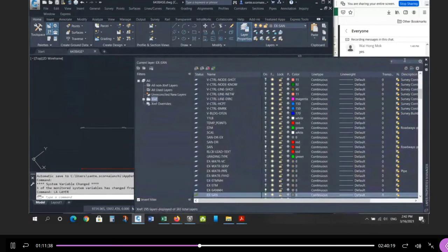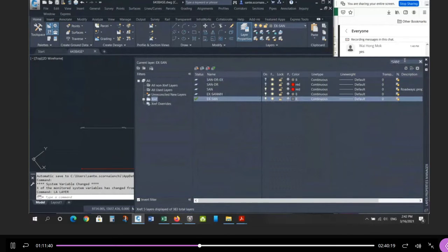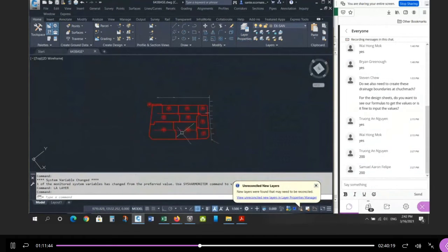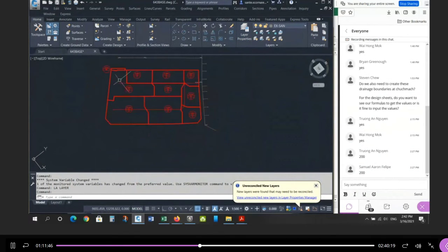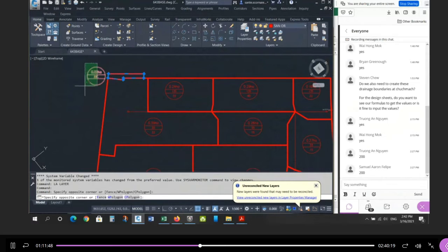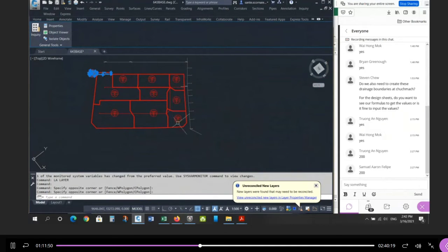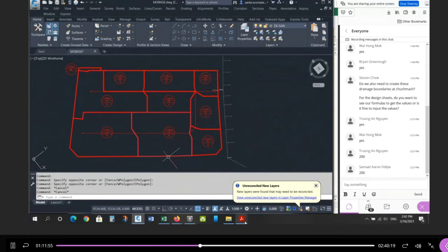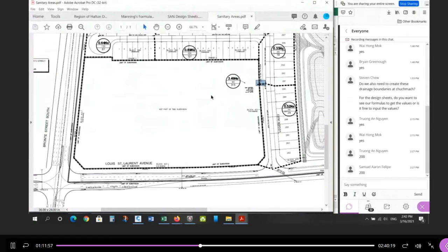If you look at your drainage area information, if you add up all these populations, don't include this one because it's going a different way, right? If you add up all the populations from these, they should all be a little bit less than 315. Less people, less flow.